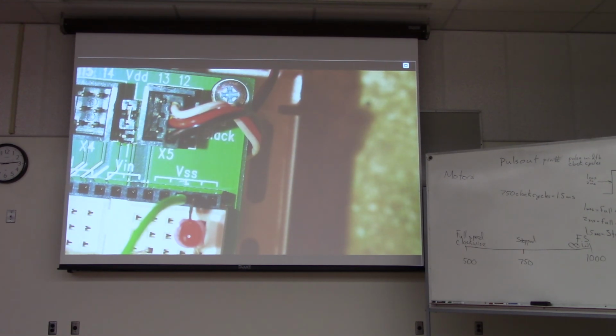So if we measured the other terminal of the battery, we would say that was a 12 volt voltage at that point. But really, ground can be any point in our circuit that we want. With older cars, the standard was to call the positive terminal of the battery ground.